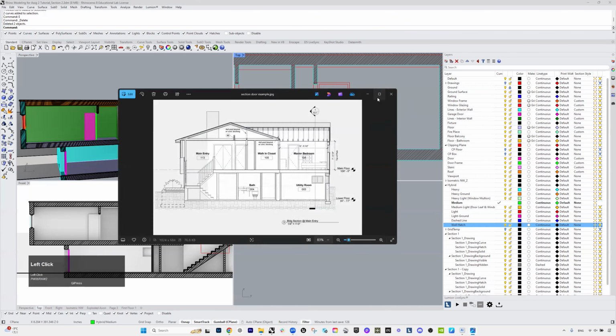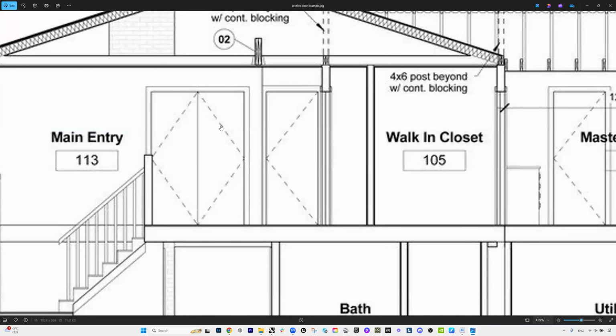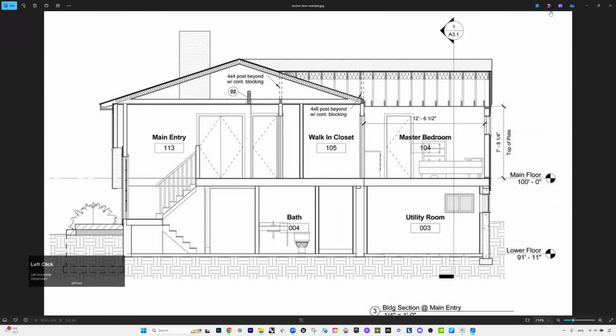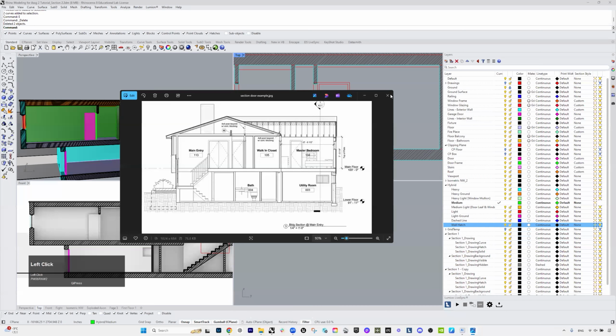This is just an image that I found. In the doors, this dash line indicates the direction that the door opens. So this is a double door. It means the door hinge is on this side and the doorknob is somewhere over here, so the door will open like this. Same thing over here: the door hinge will be over here and the door handle somewhere over here, so this door will open like this. So that's one way of showing the doors, the regular convention.